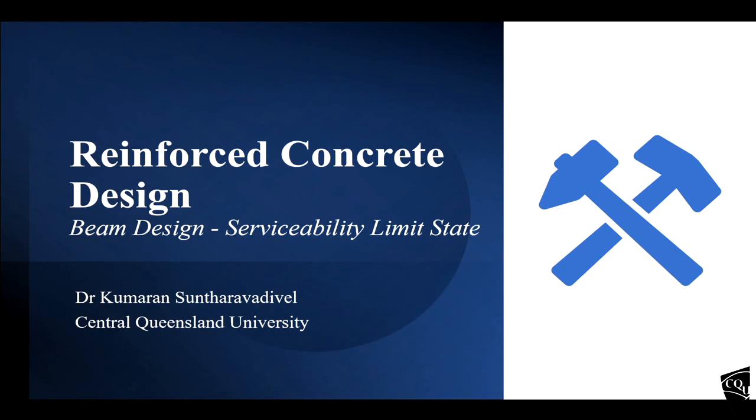If you look at those things, the dimensions are mostly controlled by the serviceability checks. The dimension of the structure, not the reinforcement, is mostly controlled by the serviceability limit state, so generally by the deflection check. So we need to do the serviceability limit state or deflection check as a first check.